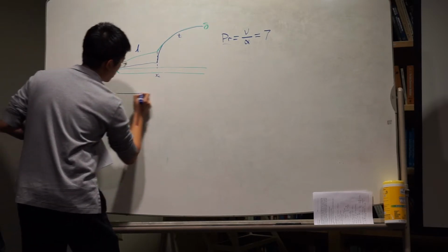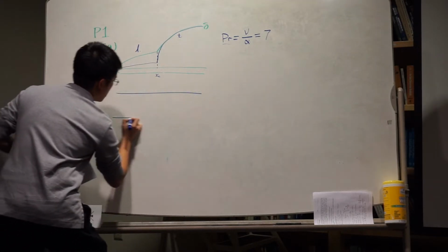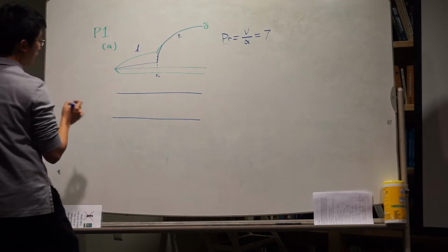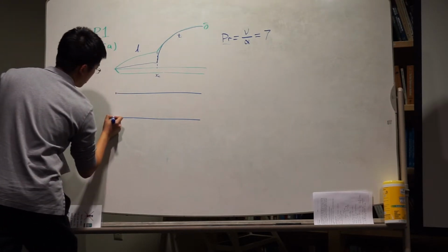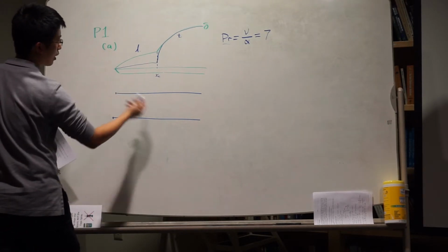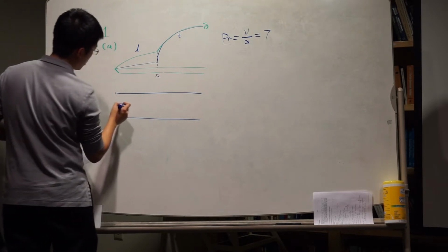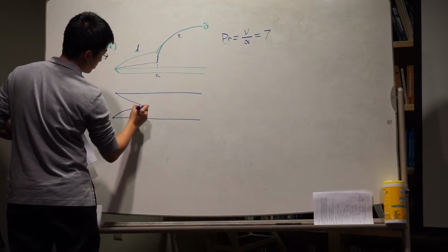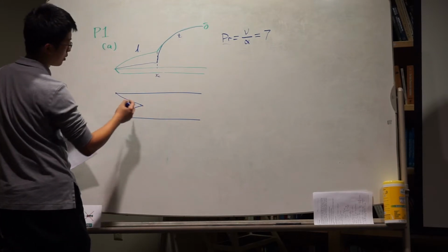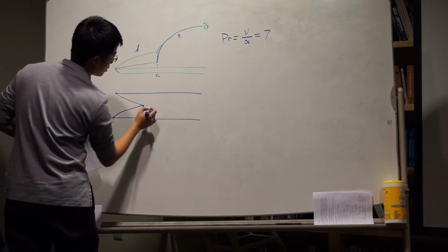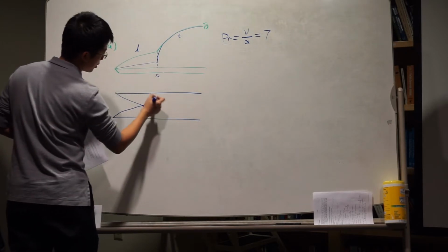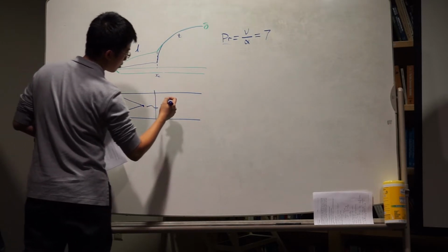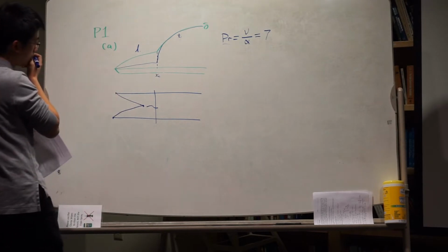Basically, it's also comparing the velocity distribution and thermal distribution. Now this case is internal flow. So we know when it enters the pipe there's an entry length, and when the two boundary layers merge, after a small distance we can say, okay, it's fully developed flow, right?